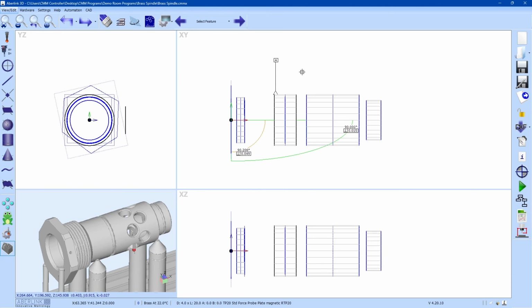So just to highlight that issue, if I go to A and this cylinder, I've got 13 microns. If I go the other way around, I end up with 8 microns, and that's because with A selected first, I'm aligning the error, or the clock, through this cylinder and running it around the entire length of this cylinder. This cylinder is longer, and if it's slightly out, which it is, the clock error gets bigger by the end of the entire surface, which is why we end up with 13. Doing it the other way around, we're aligning through this cylinder and only running the clock along this length of surface on datum A, which is obviously going to result in a smaller error.